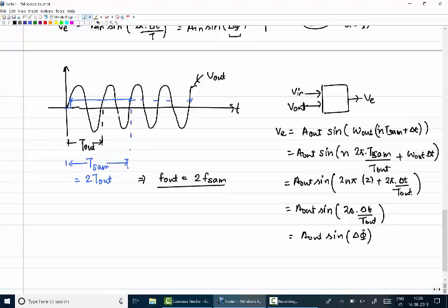Okay, a couple of observations here: I am sampling my higher frequency signal with the low frequency signal, right? This is called subsampling. The phase error delta phi which you are looking at here, is it with respect to the higher frequency signal or the lower frequency signal? It is the higher frequency signal, right? So the phase error is with respect to the output signal here.